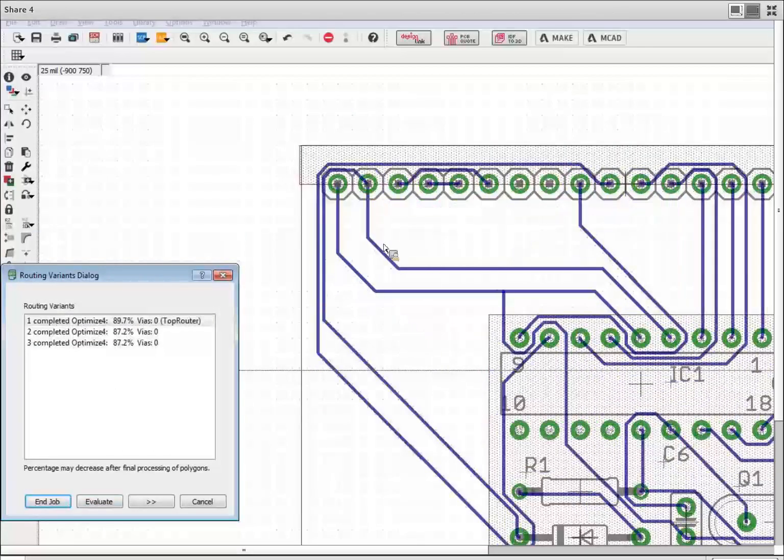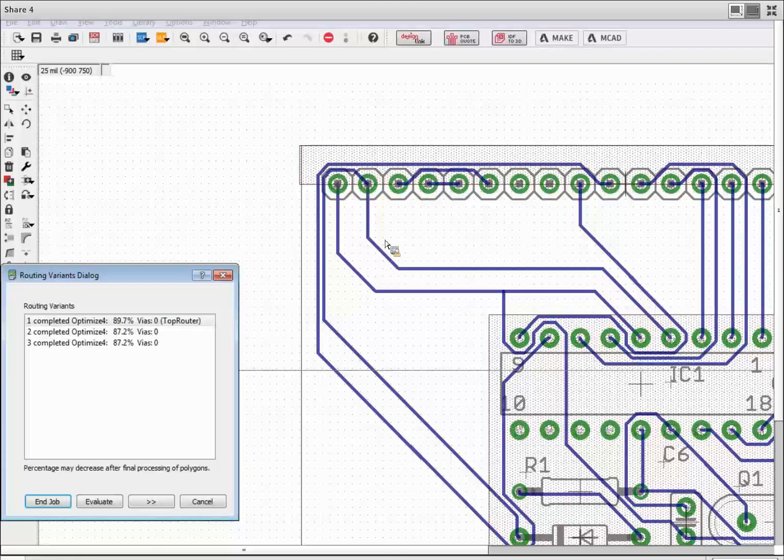Okay, so the Autorouter does respect any traces you place, and this hints at the proper way to leverage the Autorouter. Anything that is critical in your design, high speed, high power, low level signaling, anything of that nature, your RF section, those things you're going to want to route manually following your design criteria first, and then you can let the Autorouter go to town on whatever's left that is non-critical.